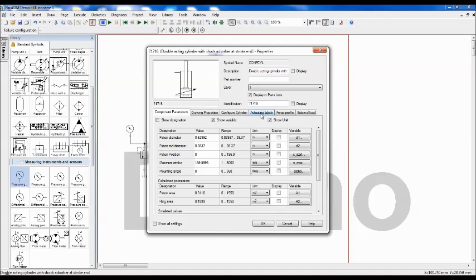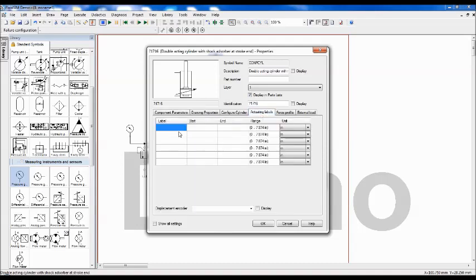Here you can add sensors. So for the name of the sensor, I'll give it as B1. Now where do you want to place the B1 sensor? What is the range? You can place the sensor between 0 to 200 mm. I want it in mm, so 0 to 200 mm. For example, I want the cylinder to be extended only half of the stroke. That means 100 mm. And after completing 100 mm of stroke, it should return back.